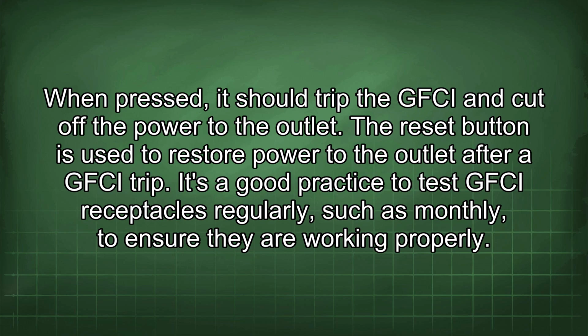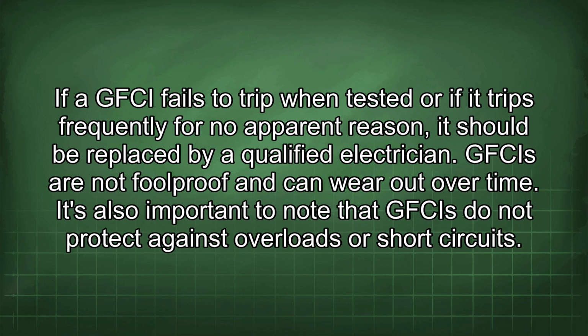It's a good practice to test GFCI receptacles regularly, such as monthly, to ensure they are working properly. If a GFCI fails to trip when tested, or if it trips frequently for no apparent reason, it should be replaced by a qualified electrician. GFCIs are not foolproof and can wear out over time.